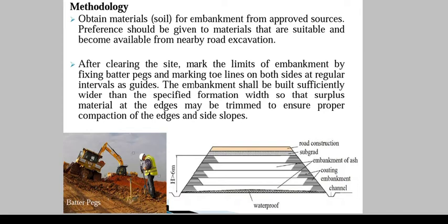So we were discussing fly ash. There are various methods. One effective method is by sandwiching a fly ash layer of thickness 1 to 3 meters between intermediate horizontal soil layers of thickness about 0.5 meters, right? Or it may be mixed with the soil, but the sandwiching method is the most effectively practiced method.